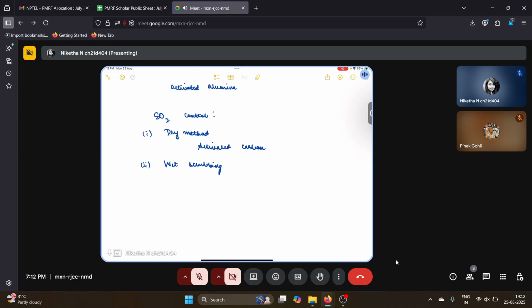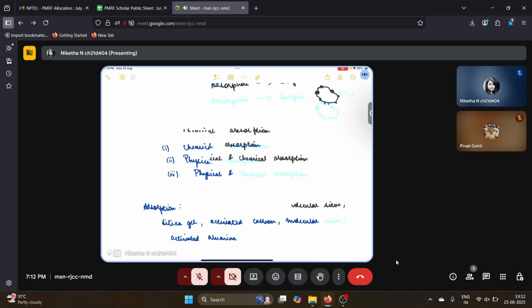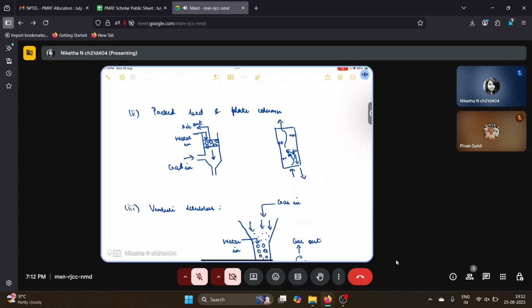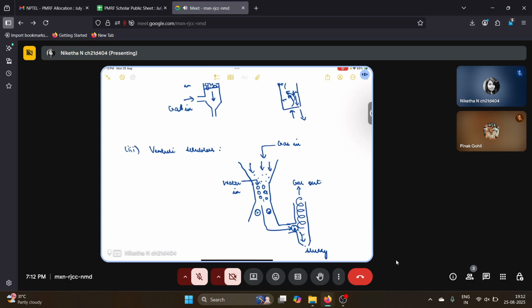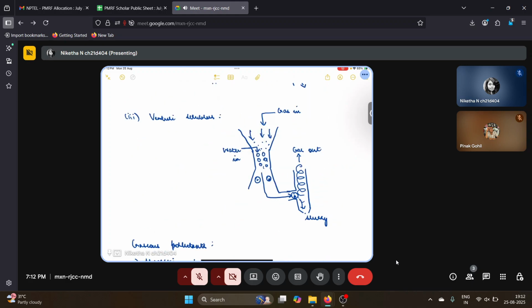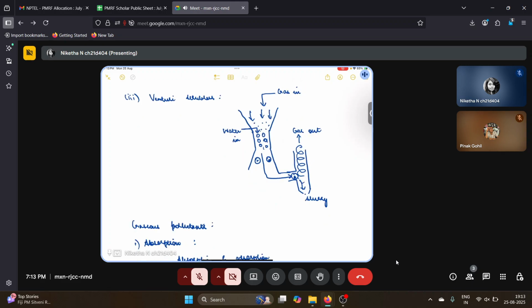For wet scrubbing, like we already discussed previously, once the gas comes out, in all of these processes, that is treated separately. In the wet scrubber here, we use lime and limestone. That will react with the sulfur dioxide and precipitate it.